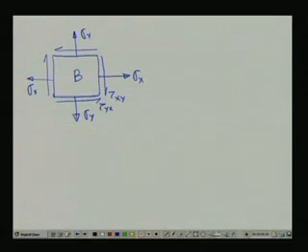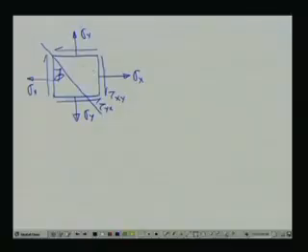One important situation comes into the picture: if you have this type of combination of sigma y and tau xy, the shear stresses and the normal stresses, then we have to find out the combined effect of sigma and tau. Not only that, we also have to find out the stress at that particular point at any other orientation.